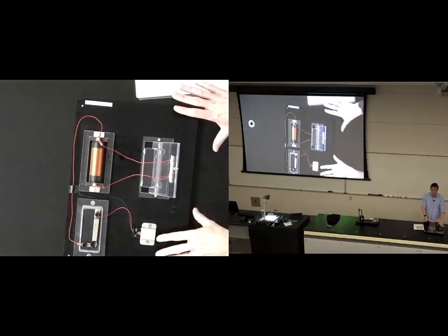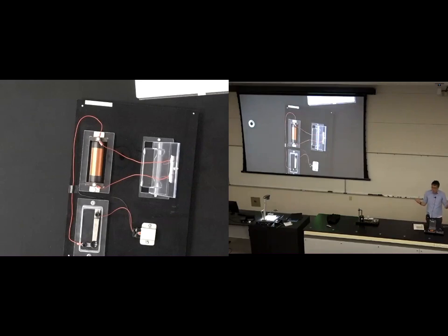And that's the crazy thing about this circuit. Although it's impossible to light the circuit with the battery, because it only provides 9 volts and you need 100 volts, the moment you switch it on, we'll see a flash of light from this lamp, because at that moment there's a big induced EMF that's more than 100 volts. The moment we switch it off, again, we'll see a flash of light in the circuit, because at that moment there's more than 100 volt induced EMF due to the large self-inductance of the solenoid.